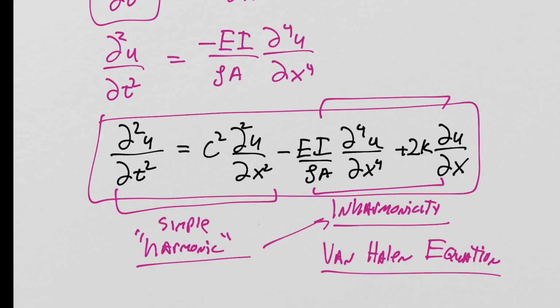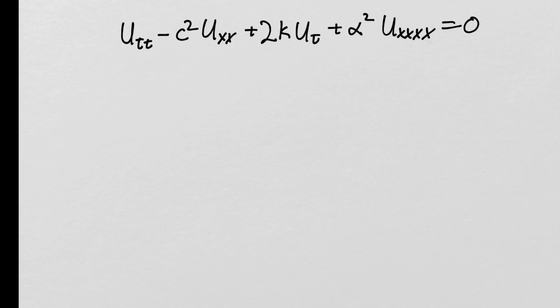Okay, so let's begin. We begin by writing it down in a neater form where we don't have to carry around all those symbols for partial derivatives. This represents the second partial derivative of u, the transverse displacement, with respect to time, the second partial derivative of u with respect to distance from the nut, which is the x-coordinate, and the fourth derivative of u with respect to the displacement from the nut.